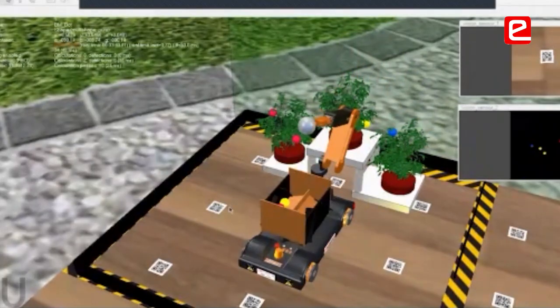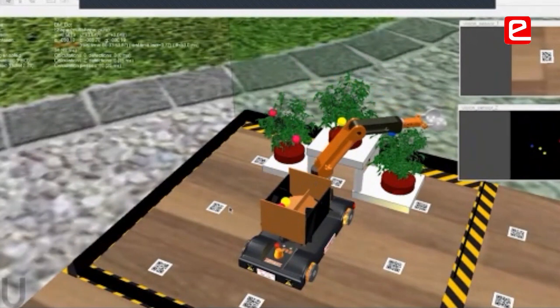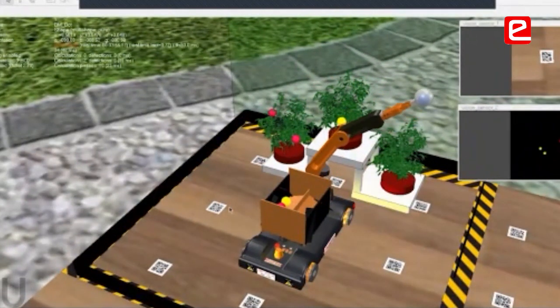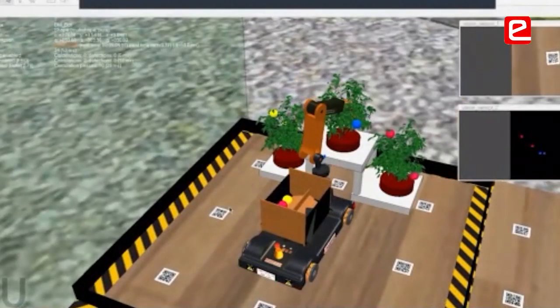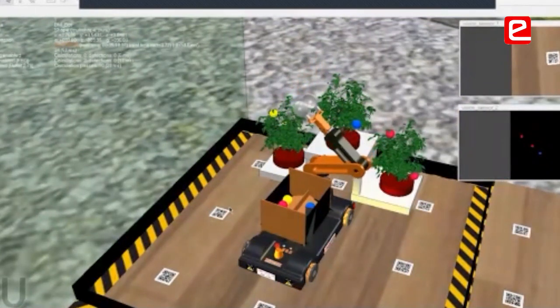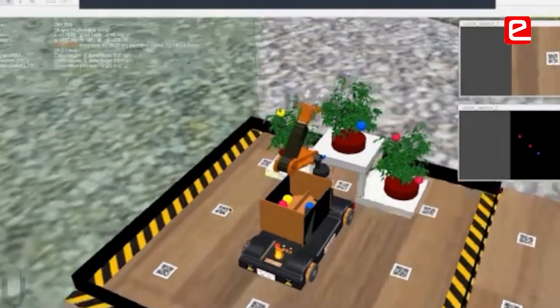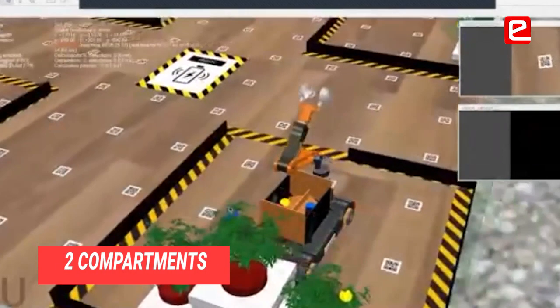When you're putting it in your trough, in your deposit boxes, you deposit it from a little bit of height, it drops in and then it tumbles onto the other side. We tested a few times, and then we came up with a trial and error mechanism for developing this optimal height from which we were able to avoid this issue. But if we could slightly increase the barrier height, which was dividing those deposition boxes into 2 compartments.